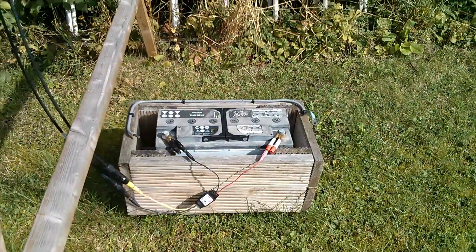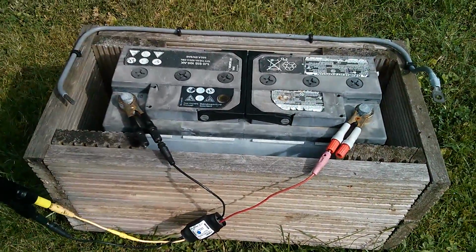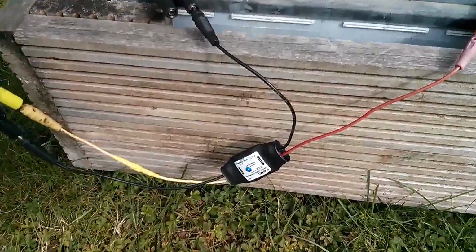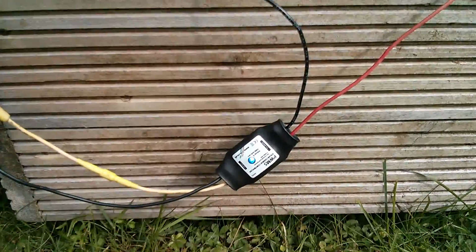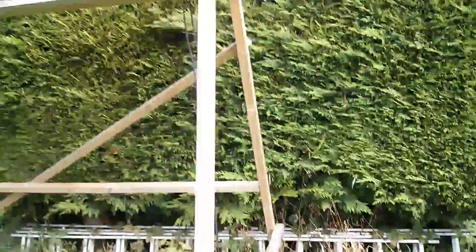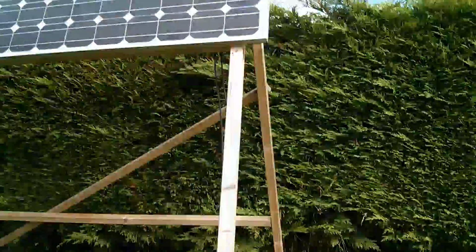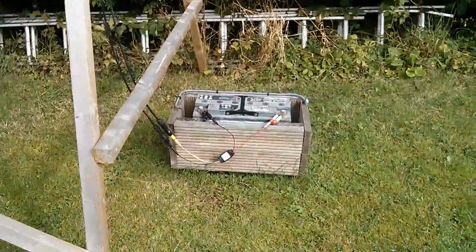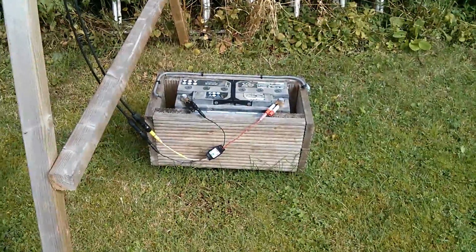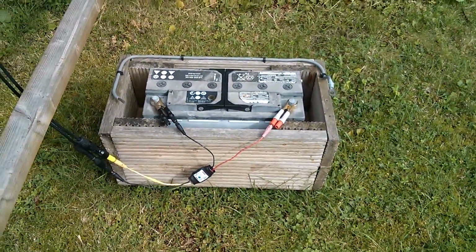Well, the plan is to take 12 volts from this big car battery, which is being charged from a solar panel via one of my PWM5 solar charge controllers. That's modulating nicely, so that's fully charged. It's actually being charged from this 80 watt panel, the right hand one. So that gives me 12 volts, but of course it's halfway down the garden. So the idea is to have the boost converter out here, boosting this 12 volts up to a high voltage.